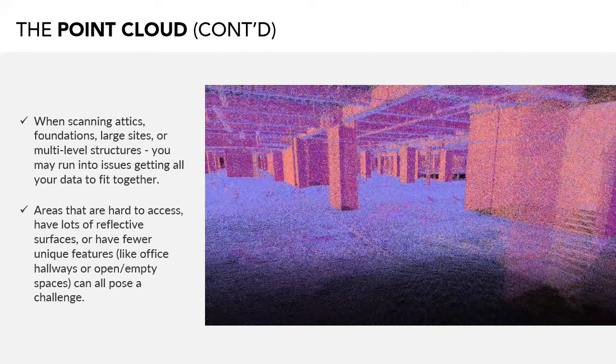So processing scan data requires that all areas have data connecting one area to another, like good overlap between data, so they can be properly glued or stitched together. Mirrors or large moving objects or a lack of significant features in your environment can sometimes trick the algorithms and make it a little bit of a challenge to put together a successful point cloud.